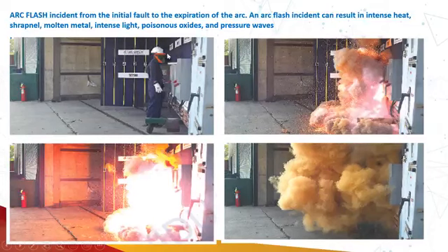Just keep in mind that the incident energy unit is calories per centimeter square, which is basically the unit for some energy which is impacted on a human body. So as we move from this center, the incident energy will decrease over the period of time.